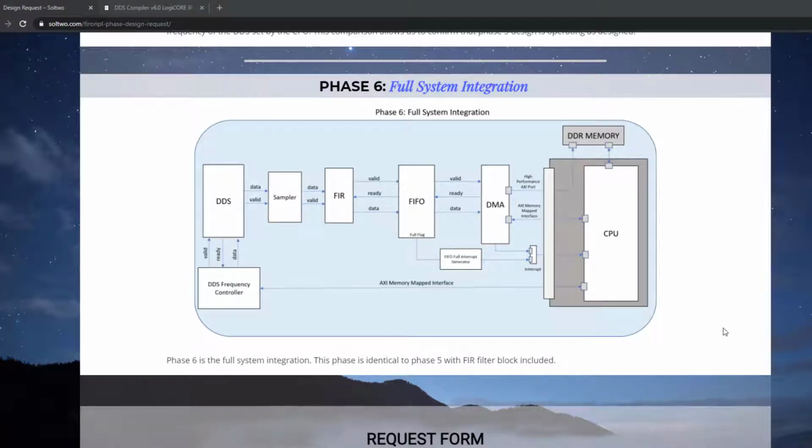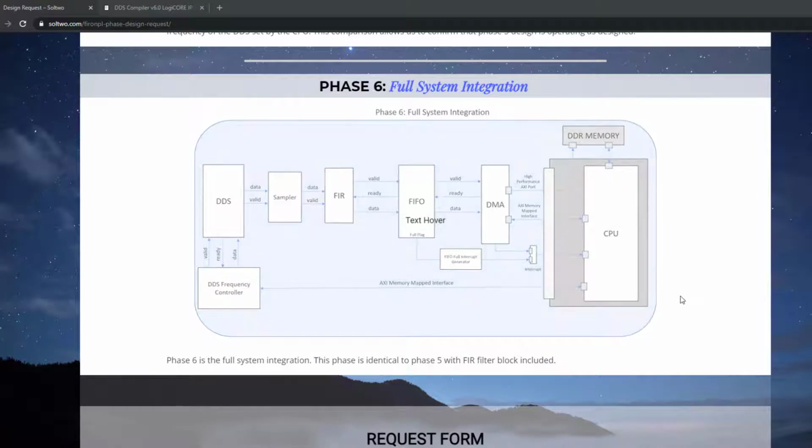My name is Erickson. In this video we're going to go into post-processing the data in Matlab. If you're not familiar with this project, it's basically a project that analyzes an FIR filter that is implemented in the Xilinx system on a chip FPGA. In the FPGA fabric you have an FIR filter surrounded by other components that is used to test and analyze that filter, and everything is done from the CPU, the configuration and the data transfer from a FIFO to the DDR memory. In the last video we talked about the bare metal application.